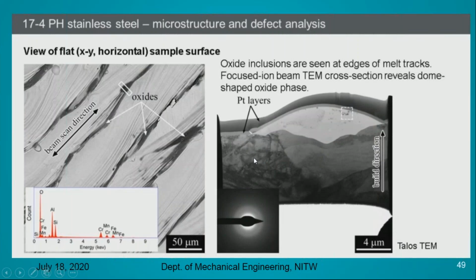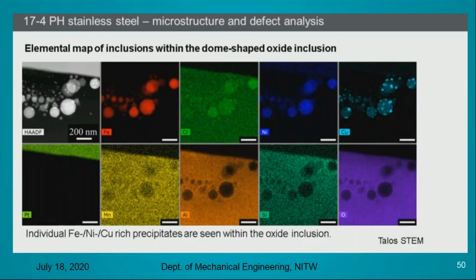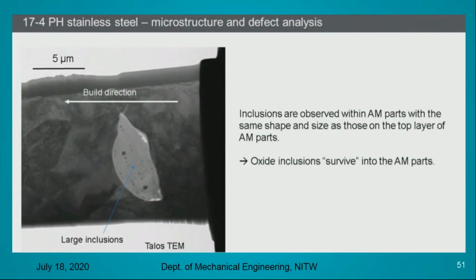Also, you can see that when you use recycled powder, there might be a chance of formation of oxides in the successive layers. That can be analyzed with the help of the SEM process. It means there is a formation of successive oxide layers over the deposited layers, which can also be analyzed with the help of elemental mapping. These oxides are going to create some inclusions in the fabricated components.